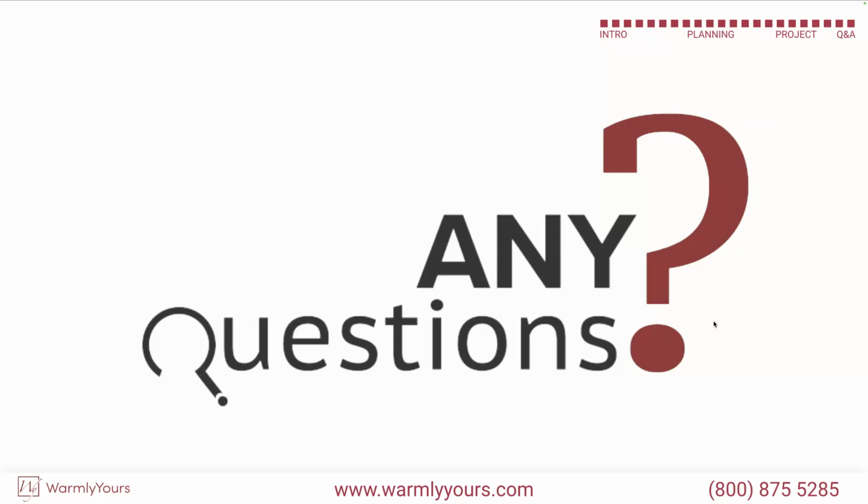Correct. And so that's a very, very good question, Dondi. Thank you for asking that, because we do run into people who say, I want to do a 3-season room and I'm thinking about putting an LVT out there. And we have to say, well, you might want to rethink that, for the reasons we just talked about. One beautiful thing though is if your client did decide to do that and self-leveled the whole floor, put on their LVT or LVP product, and if they decided in a year or so that it wasn't as hot as they thought it would be, they could pull that back off, since they just floated it over the already leveled floor, and then they could install a tile over that self-leveled floor probably, right?